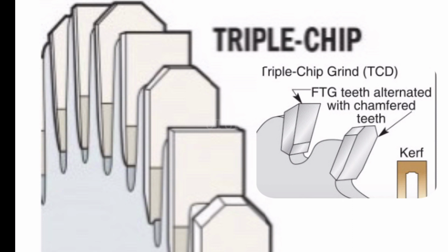Good quality cuts from the TCG on the melamine will often result in a fine smooth cut quality along the top edge of the melamine, which will have pristine sharp corners. Which is the pro. The con is, as the blade exits the bottom side of the melamine, it may chip off a little bit as it exits the plasticized bottom.